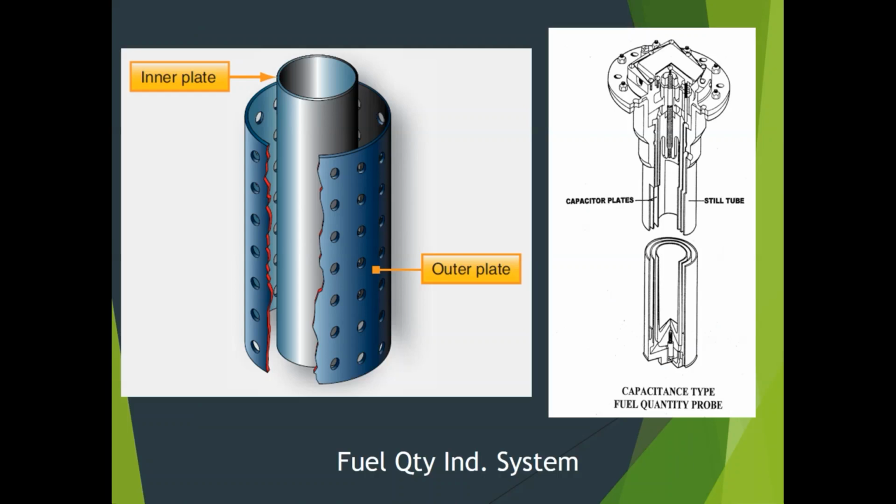This is actually sitting upside down. Typically these are installed from the bottom of the wing. Okay. Some are installed from the top, some are submerged, they're submersible. Okay, this is one that's designed to be bolted into a panel. Actually, this one's probably a top panel one. There's a panel on top of the wing you open, and this is sitting just underneath the skin, just below the skin. And then there would be an electrical hookup at the top to tie it into the system.